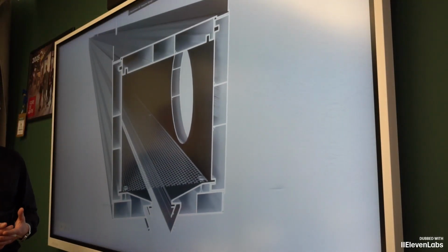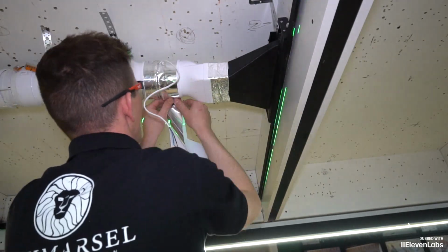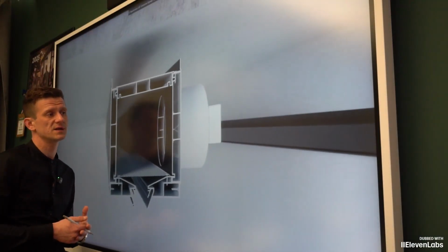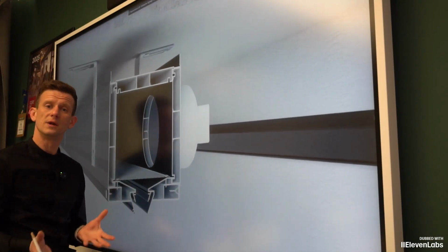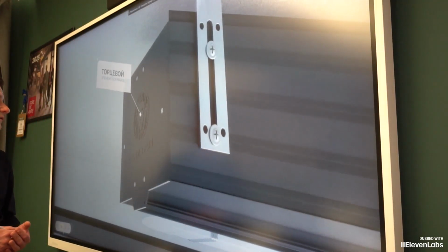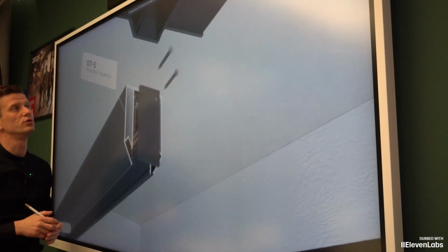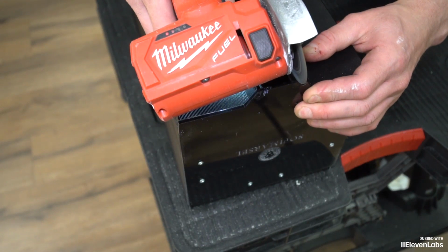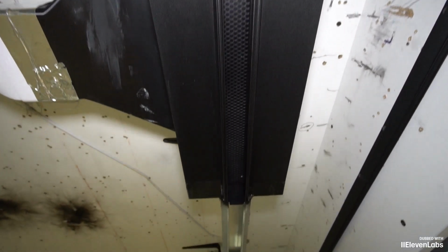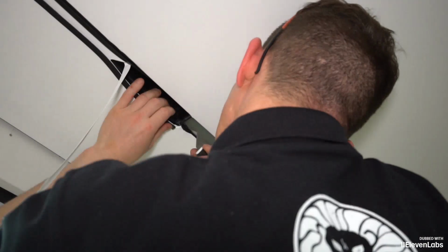I also find it important to emphasize that all gaps in the diffuser, as well as the ventilation leading to this diffuser, must be sealed, so that the effect of hyperventilation is not created and your fabric is not sucked to the base ceiling. In joining the AIRPIPE with the magnetic track system, we use only one end element, which is on the AIRPIPE itself, and we recommend making slight notches with a grinder or some other tool so that it can be neatly fit the film at the joint between the AIRPIPE and the magnetic adapter.